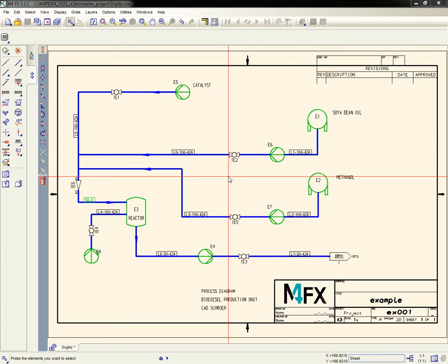One of the most common activities during the P&ID design process is the need to adjust the layout of existing equipment to accommodate new equipment or to make space for a design change. This must be done in such a way that the drawing's integrity is not affected. For example, items must remain connected and line labels and other related text should remain legible.